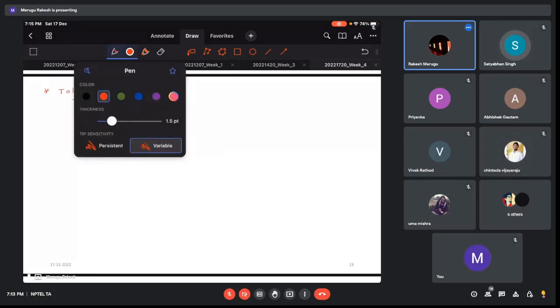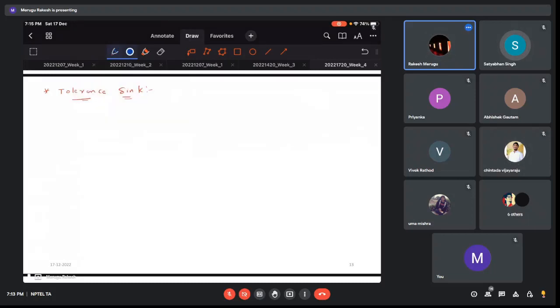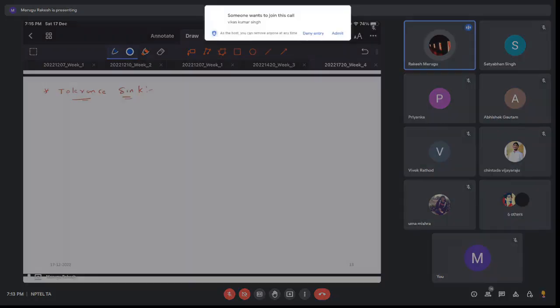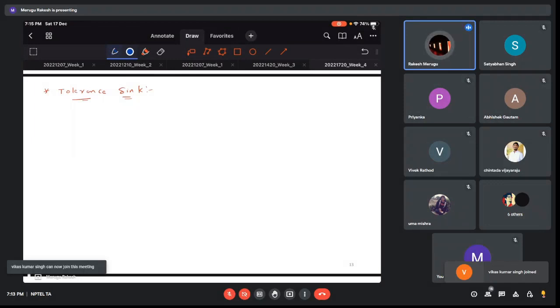So this is mainly in the design aspects. People will intentionally not give the tolerance for some part, so that if there is any tolerance accumulation they can fill it in. There is no need to give tolerance for every part in an assembly. You can leave one part without any tolerance so that you can calculate according to the dimensions finally. It is for easiness of the design process.